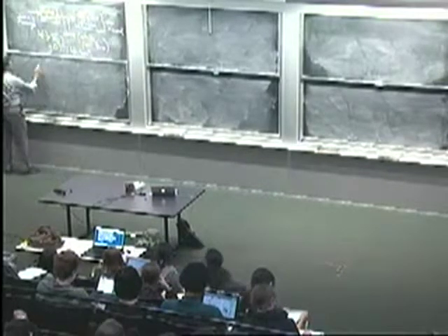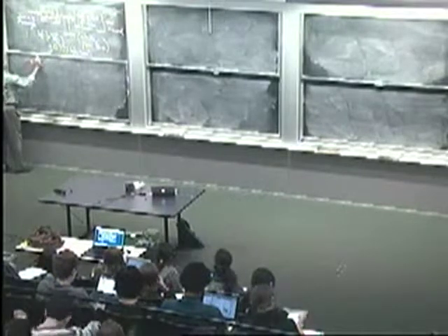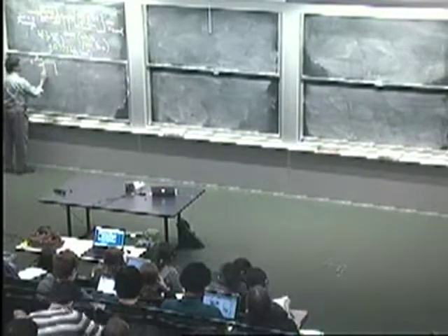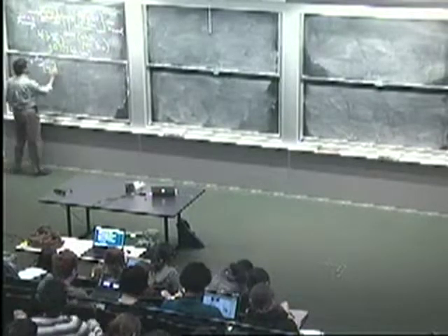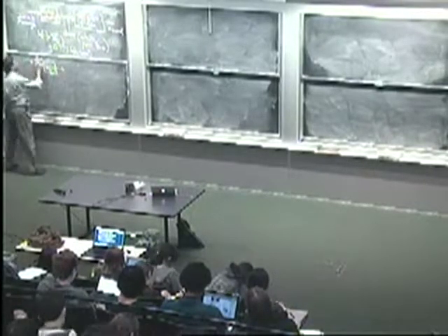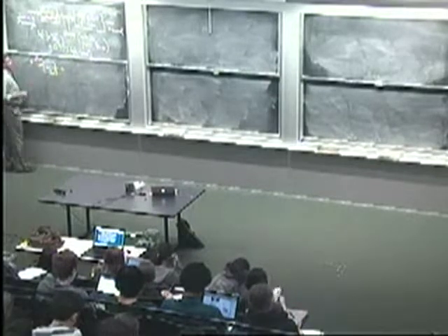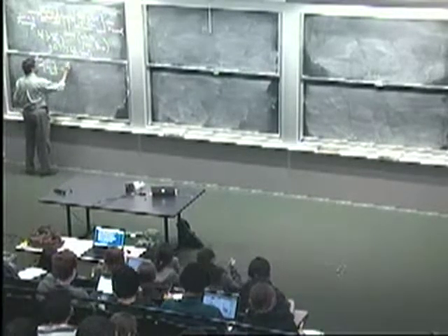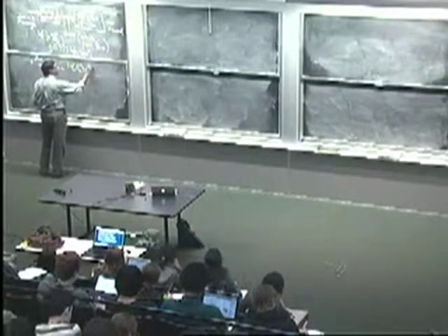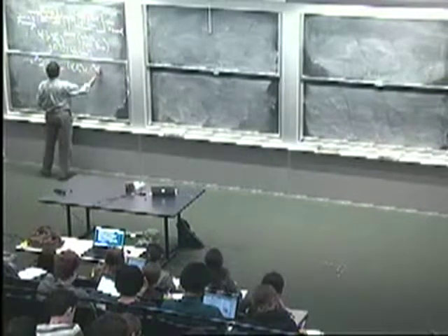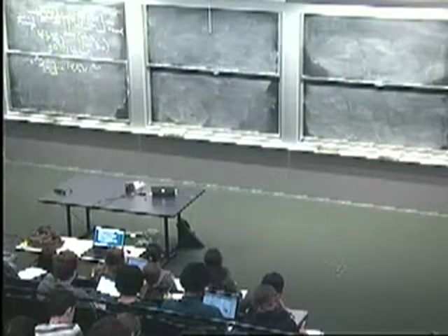So we already know that if you have e to the j omega n going in to a system with frequency response H of omega, so an LTI system with that frequency response, let me make this a specific frequency omega naught, what comes out is the frequency response evaluated at omega naught multiplying what went in.